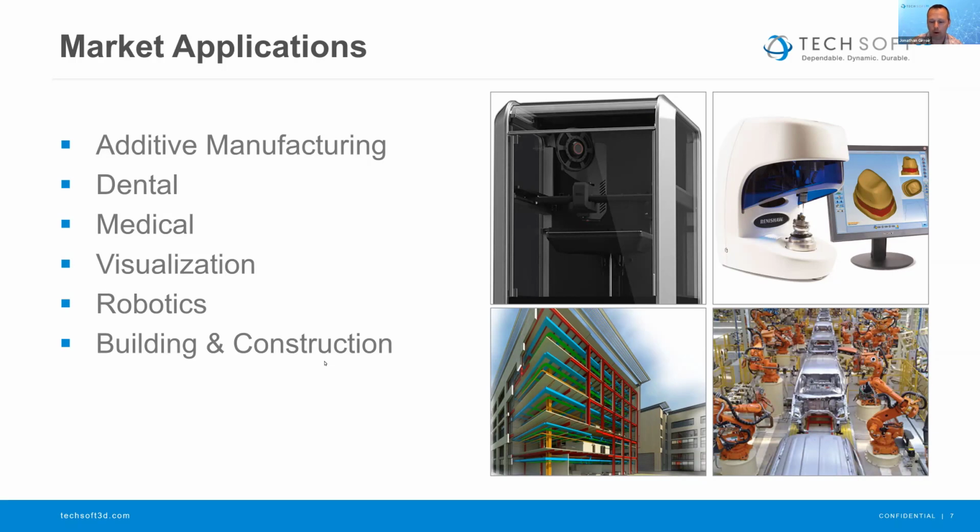In robotics, one of the powers of this API is if you have numerous solids, it is very quickly able to determine if they're interfering with one another. That's important for robotics, because you wouldn't want to drive a robot arm into, in this case, in our image here, the car body. So can I simulate how this robotic arm is operating and do a lot of clash detection, which Polygonica does very quickly in our simulation step, such that when I upload the program and actually execute it in the real world, we are confident that that doesn't happen.